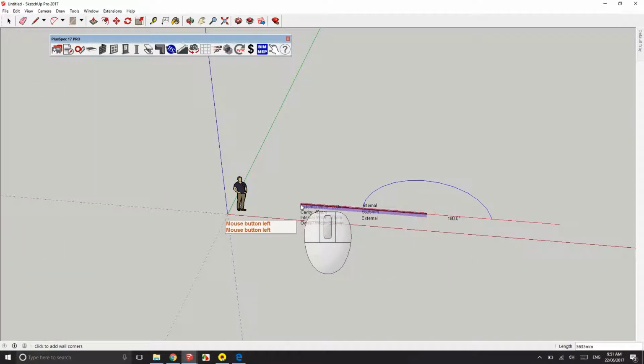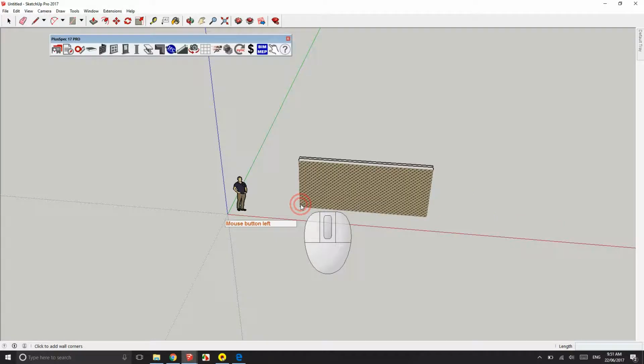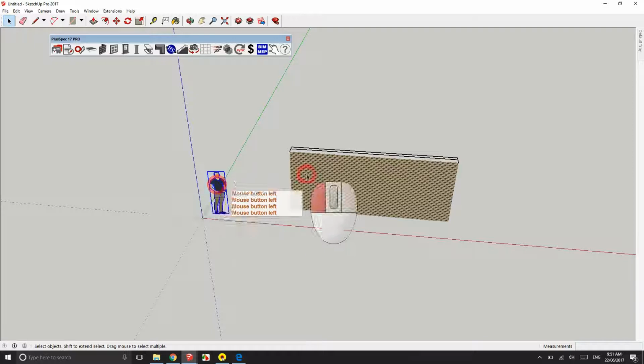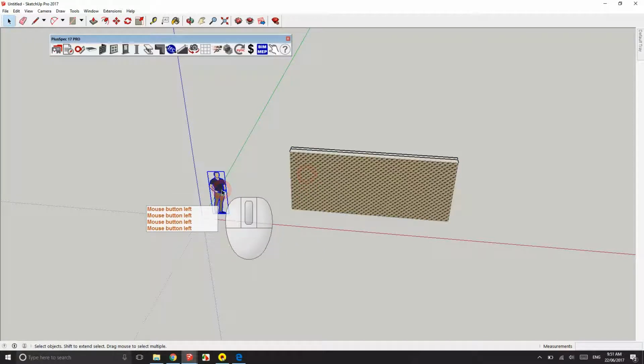Now to draw one wall without creating a loop, I would double click. Okay. Now the computer still thinks I want to draw more walls here. You see my mouse pointer is white, that little arrow is white. However, if I went to here, it would now select things, you see. So get used to doing that, guys. It's a big help. Okay, I hope that helps with these things. It's important. You can watch this video back several times to get the hang of it.